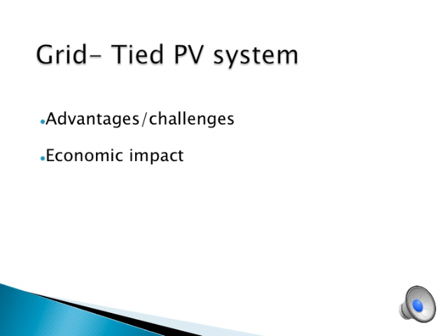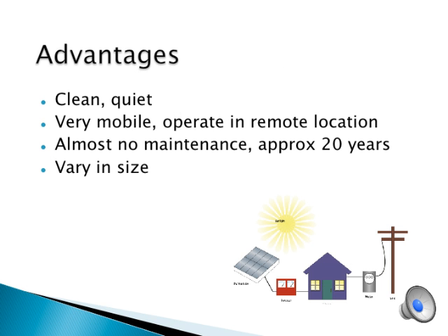The third configuration is the master-slave configuration. At low irradiance range, only the master inverter is operating. As the irradiance increases, the slave inverter kicks in. The configuration has a higher efficiency, particularly in the low irradiance range.